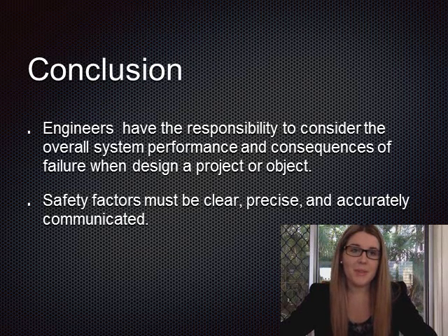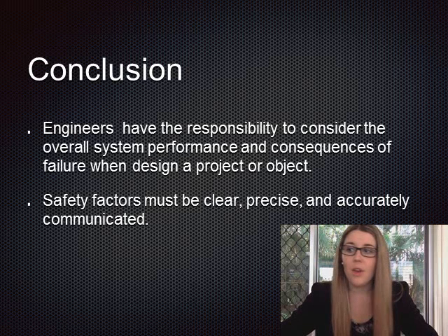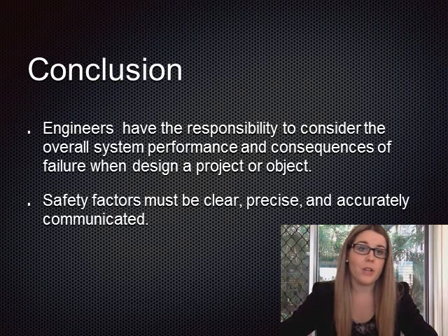Overall, my closing points for this presentation are: many people think good engineering uses calculations to reduce the size and the strength of components to a minimum. However, experienced engineers have the responsibility to consider the overall system performance and the consequences of failure when designing a project or an object. Safety factors must be communicated clearly, precisely, and accurately to the project team throughout the entire design process.